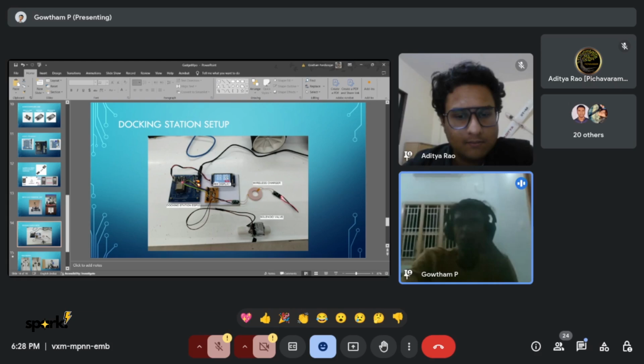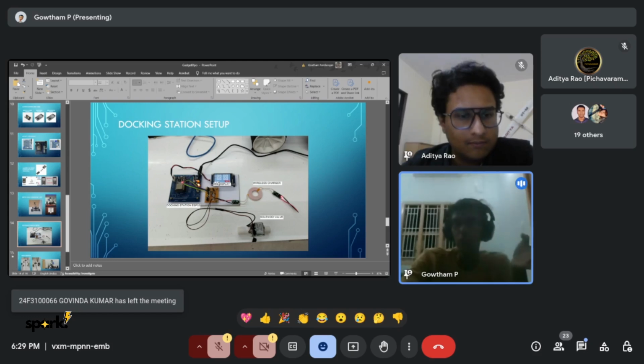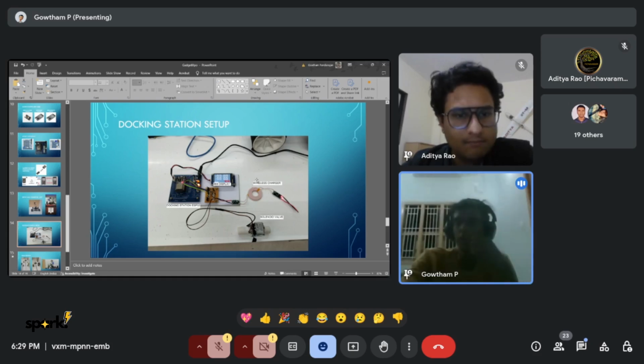That is here. There will be continuous input from the robot, such as voltage from the battery and the weight of the water storage tank from the load cell. If the voltage of the robo battery falls below a certain level, the robo will automatically go to the dock, and will automatically charge itself using this wireless charger. And if the water storage level is low, it will automatically control the solenoid valve, and it will also fill up the tank.